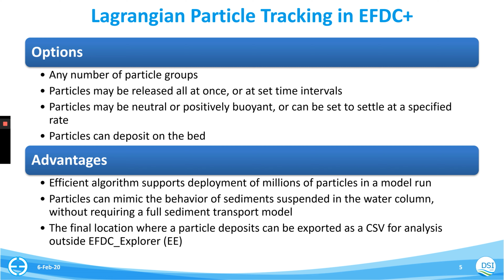As it says up here, you can release them all at once or set a specific time interval for the release. We can specify a settling rate. That is a really nice feature, especially when you think about the analogy that these particles can have to sediment particles. You assign a settling velocity, and these particles behave in largely the same way that a sediment particle suspended in the water column might.